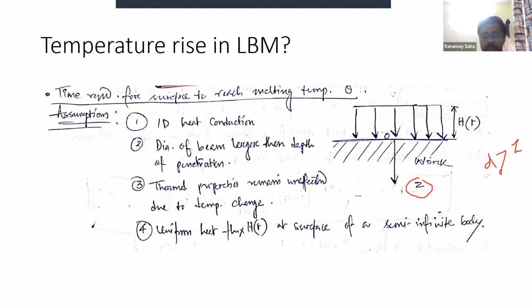Actually, that doesn't happen, but to derive the temperature rise inside the workpiece, which is a highly complex phenomenon, we have to make some assumptions. So this is one of them, that the thermal properties remain unaltered with increasing temperature. And uniform heat flux H at the surface, so the heat flux also remains uniform throughout the operation. That is the fourth assumption here.